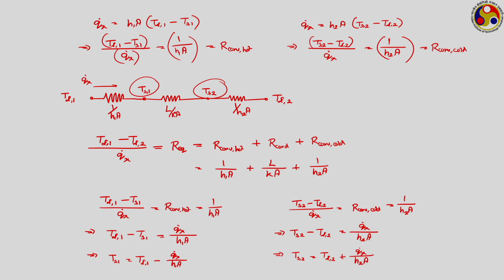So, we do not need to know the values of the two surface temperatures Ts1 and Ts2 to get the Q̇x, rather using the value of Q̇x we are getting their values later on. So, this way any one dimensional steady state heat conduction scenario, at least in Cartesian coordinate, can easily be reduced to such kind of series of conduction and convection resistances.